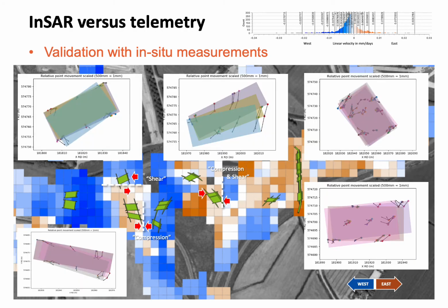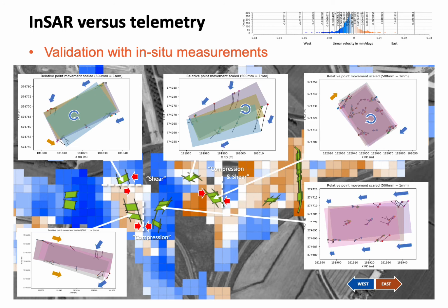Individual bridges and their telemetry measurement are displayed for comparison. We can see a good match between Sentinel-1 stress interpretation and the corresponding bridge's telemetry interpretation. With a rigorous analysis of the Sentinel-1 time series, we were able to maintain the same spatial resolution, from LOS displacement input to horizontal deformation output, and convert InSAR displacement from data to information applicable to infrastructure monitoring.